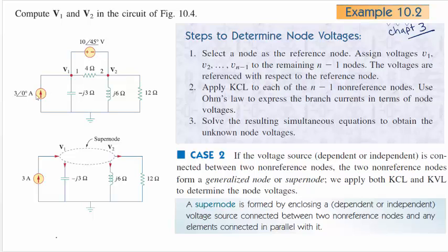But there is a phase difference, as is typical in these kinds of circuits, where current and voltage are not in phase with each other. So the thing you have to recognize here is that you have two main nodes, and a voltage source between those two main nodes. That causes us to create a supernode right here. Again, I've re-clipped things from Chapter 3 to remind you what the process is for recognizing and creating the supernode.